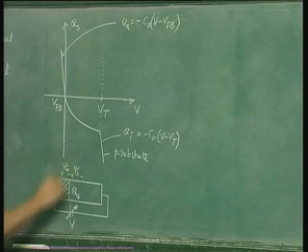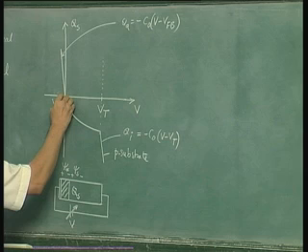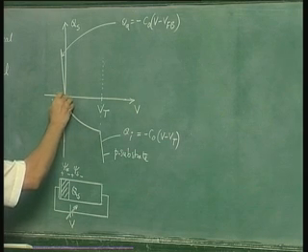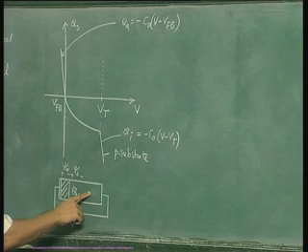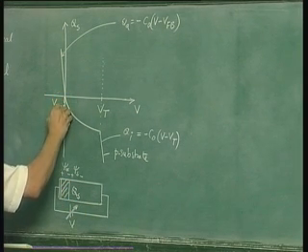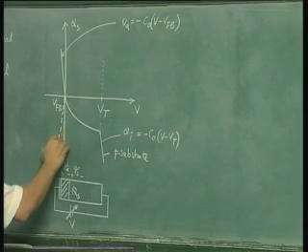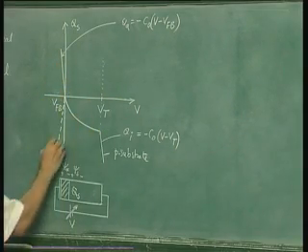Now on this diagram, if you want to draw the picture for n-type capacitor, it would be the following. For n-type capacitor, the accumulation charge is negative, because if substrate is n-type, then accumulation means electrons. So therefore it is simply a reflection of this curve on this voltage axis.